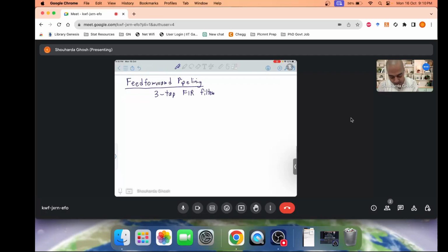Okay, so you have the input signal x[n], then you have the first delay x[n-1] and the second delay giving you x[n-2]. You take the first tap multiplied by h0, second tap multiplied by h1, third tap multiplied by h2.